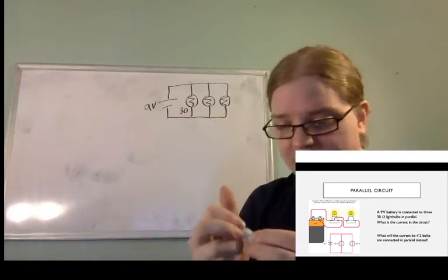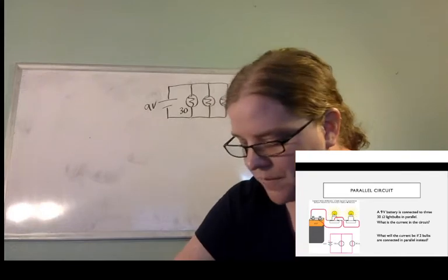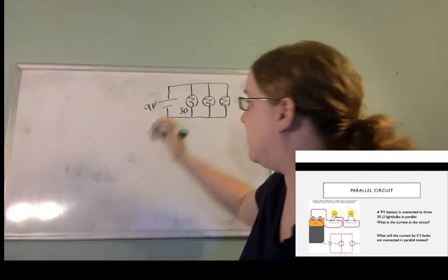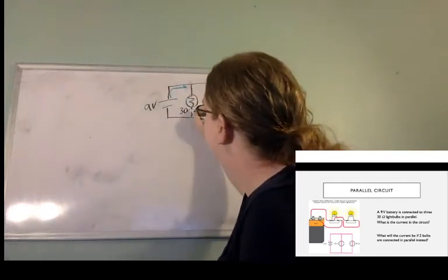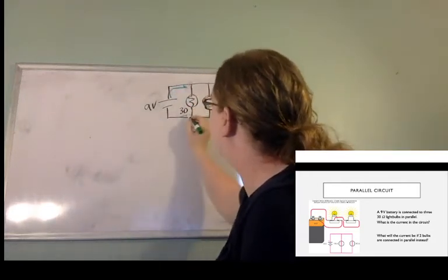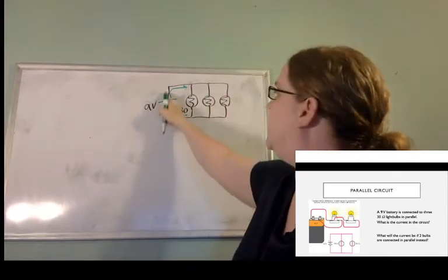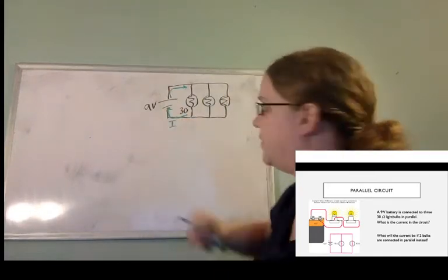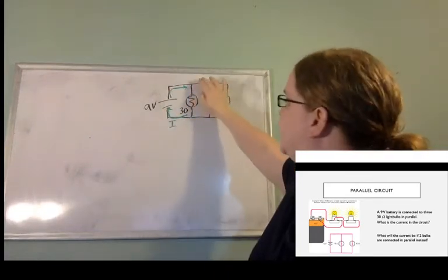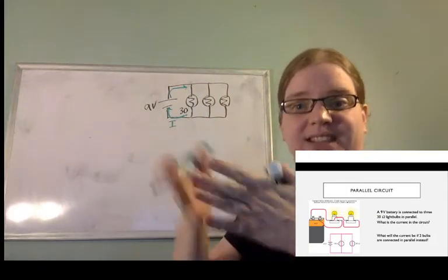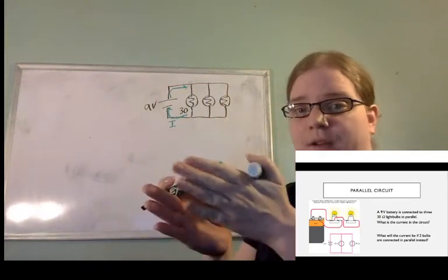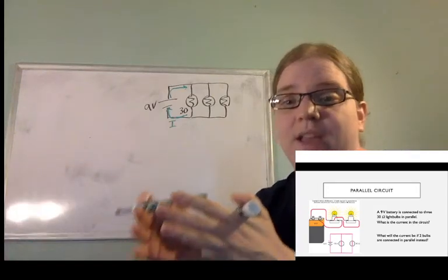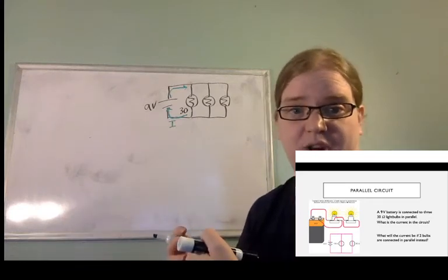Because the other thing is, what I'm finding here is the current through the wire just coming from the battery. Just this part. Be careful about that. Anything in this part of the wire directly with the battery, that is the current we're finding. Because when it gets into these paths, like we saw with the hill, it can split. So your total amount of current is like having a big water pipe, and then it splits into 3 other water pipes. You get a portion of the total current down each branch.